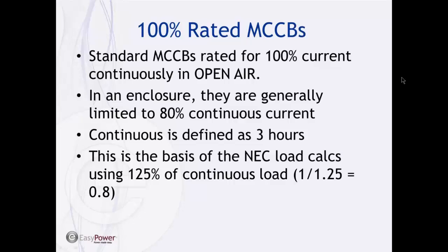Okay, finally we're going to talk a little bit about 100% rated molded case circuit breakers. As we mentioned before, a standard molded case circuit breaker, UL 489 breaker, is rated to carry 100% current continuously at 40 degrees C ambient in open air, which you're never going to encounter in the real world.